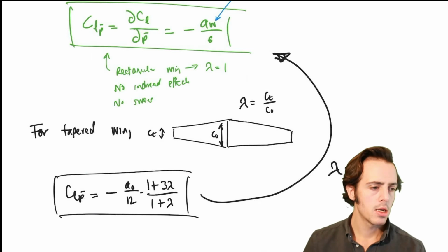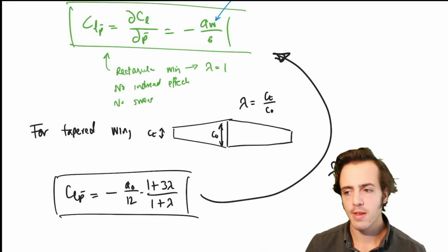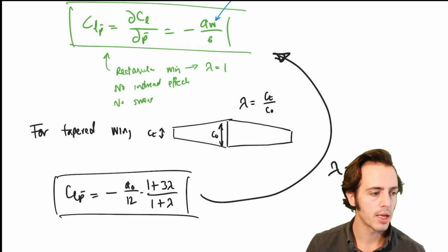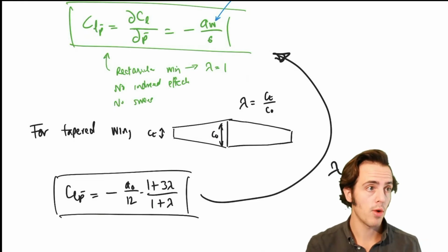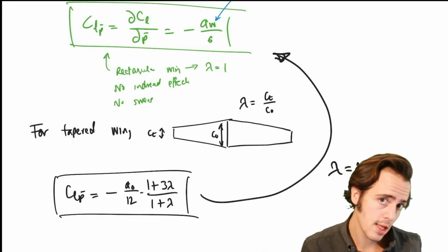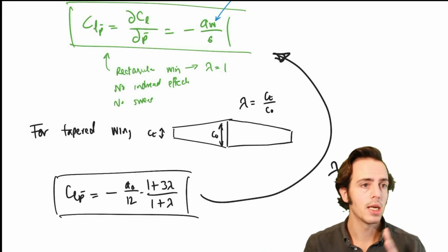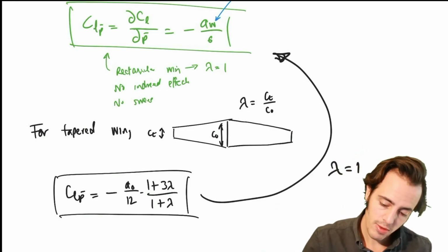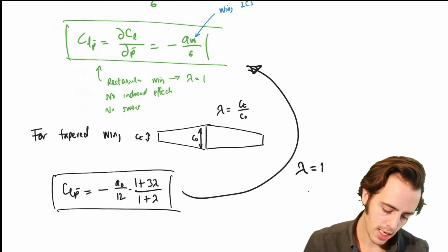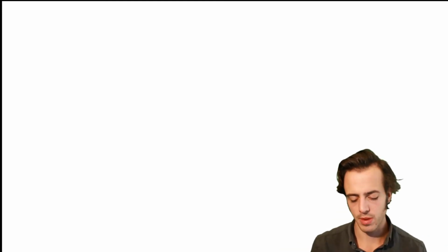So we've gone through a simple estimation of the roll damping derivative, and we've introduced this idea of the non-dimensional roll rate to help us work this out, because you'll see these non-dimensional derivatives more and more when we actually end up developing them. These derivatives themselves are just numbers. They're numbers that we work out, and we use them to help us determine how different aircraft perform compared to one another. And like I like to say, they are effectively the soul of the aircraft, how it wants to move in the sky and how it's going to respond to perturbances.